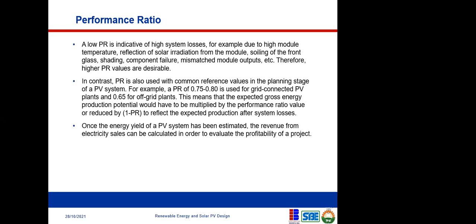Most times when I'm doing my calculation on energy yield, you want to calculate the amount of energy that could come out of a system. When you're doing that calculation, in most cases, I use 0.75. So I discount 25% from what the nameplate capacity is telling me. The same thing applies when you're doing your battery calculation. We'll get to that maybe tomorrow or next month.